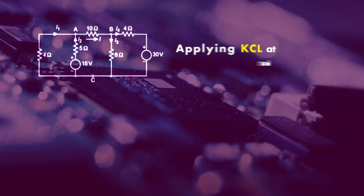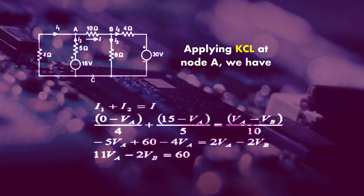Now this nodal method can again be explained by taking an example. Here you can see there are two nodes, node A and B, and two voltage sources: one is a 15 volt source and another is a 30 volt source. Now apply the KCL at node A. I1 is an incoming current, I2 is also an incoming current, and I is an outgoing current. So after applying the KCL at node A, you can write I1 plus I2 is equal to I.